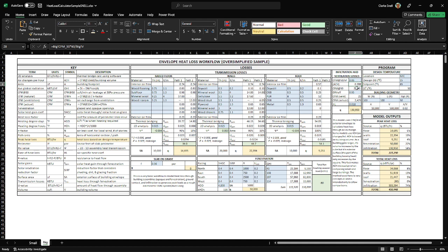That's basically taking the total CFM, which is cubic feet per minute. Then if it's per square foot, we need to know how many square feet there are in surface area, so we can get the full square footage. We can use that to get an air exchanges per hour, which is the way sometimes this is done. In other words, you need the volume then. If you know how much air your envelope is leaking, then if we know the volume of the building, we can figure it out. This is per minute, so we have to change it to hours and bring in the volume. You can look at how that works, and we've got an air changes per hour.